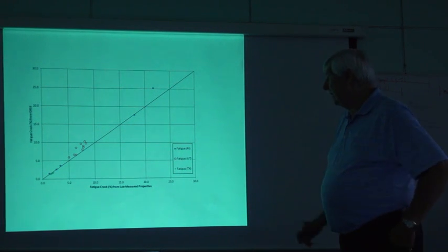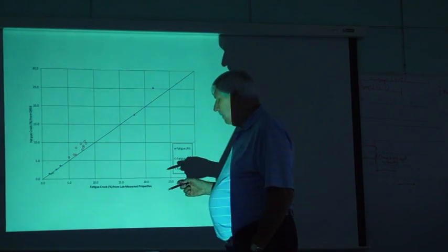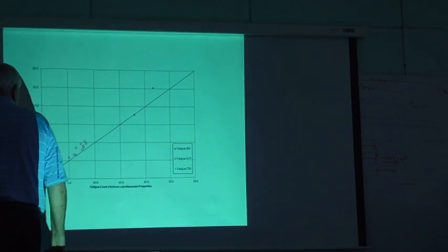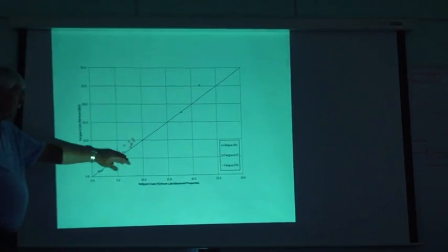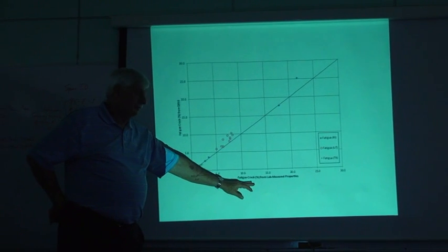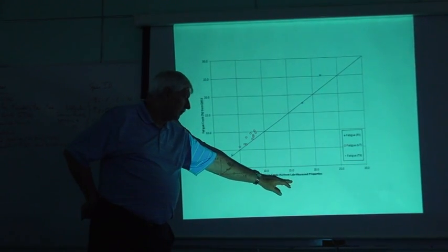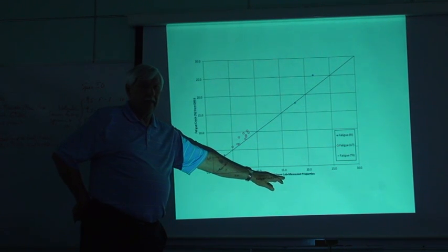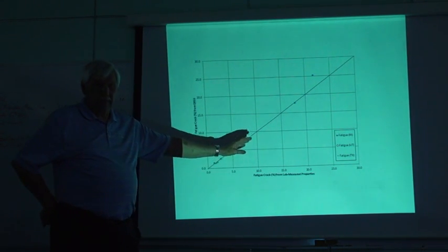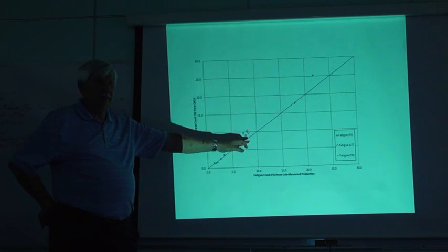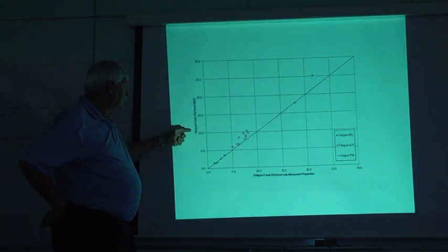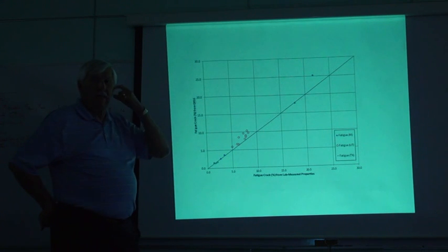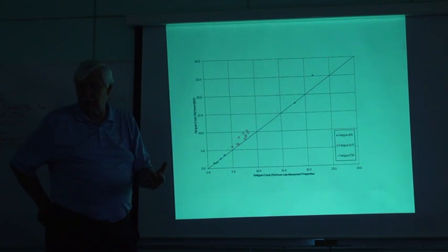Okay, you can't see it real well, but what we have now are a series of plots of the three locations. If I were to predict fatigue cracking here from the laboratory measured values, in other words, we actually ran E star at the effective temperature and frequency, here is the fatigue cracking that we would generate from the short-term solutions, the closed form solution of the NCHRP.